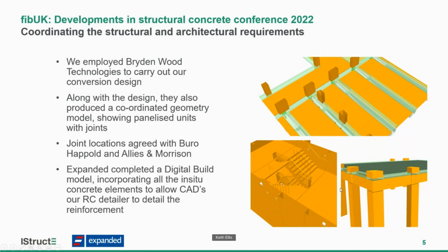There was a lot of work done. We took this model and presented it to the design team, and we spent a lot of work getting these joints agreed. It's not simply putting them where the architect wants, as there are manufacturing constraints on where the joint could go, the maximum size of unit to be transported, or the bed size in the factory. So the basis of all our work was these models, really, the in situ model plus all the precast.